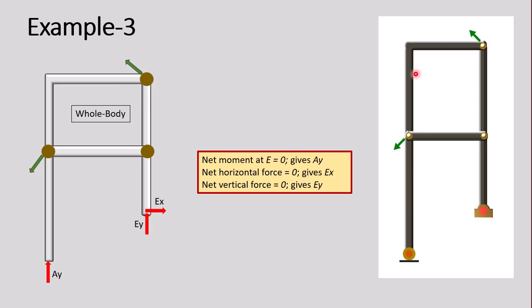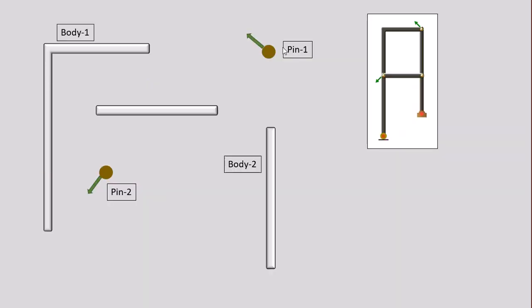So now we will get to the free body diagram of the components. We have an L-shaped multi-force member, a two-force member, and a vertical multi-force member, and 2 complex pins. These are the components. Let's add forces. Force from the roller, Ay, already known.